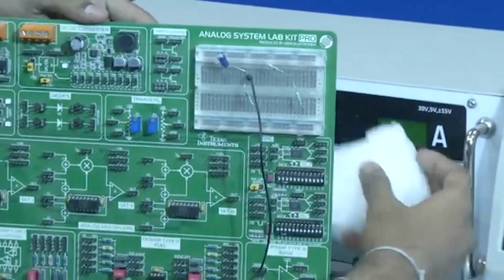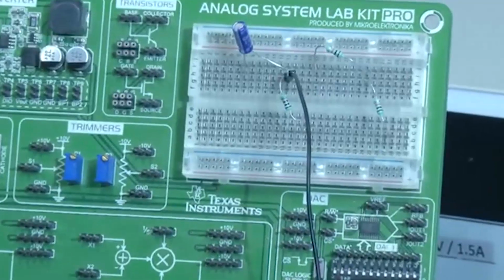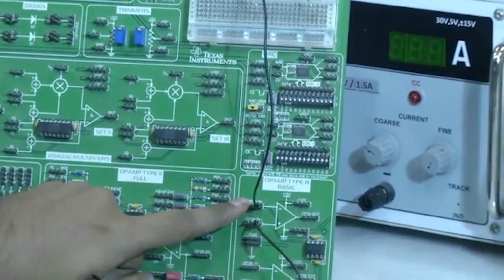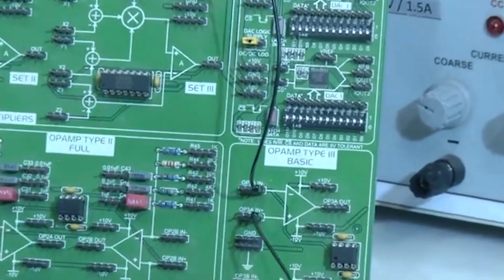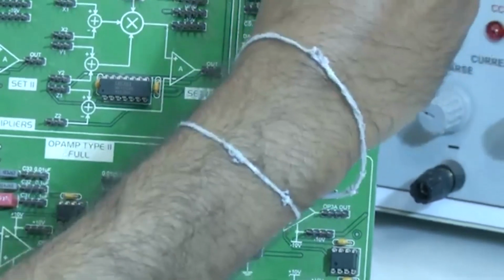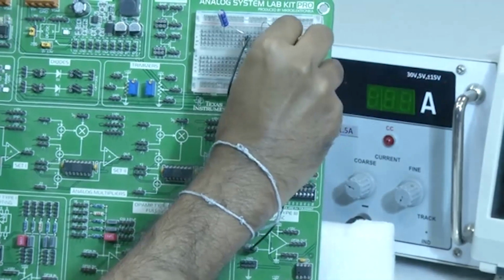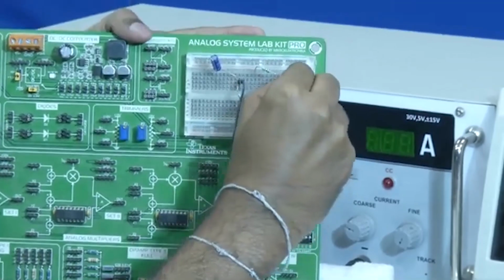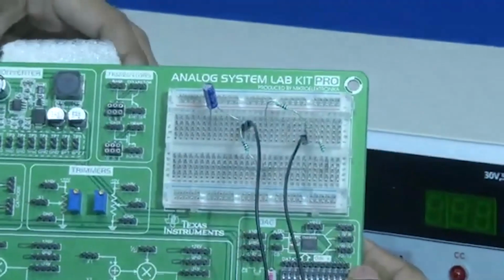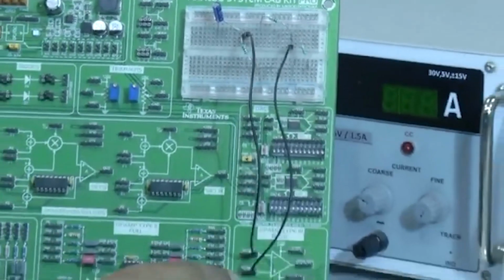right. We can see here the junction of R and C to the negative of our op amp, right, it is connected. So the other one to the positive terminal should be connected to the junction of the 10K 10K resistors. So, we can see here. The junction of the 10K and 10K resistors, the jumper has been connected to the positive terminal